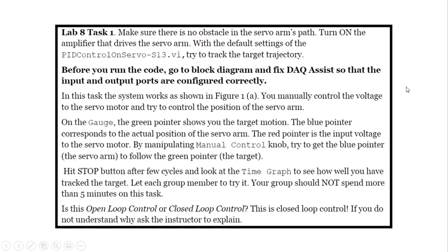So let's see. Task one is pretty much what I just said. Download the VI and make sure to fix the DAQ Assistant in the block diagram so that you map the correct input and output ports that you're using. Remember, I'm using AI 1 and then AO 1.